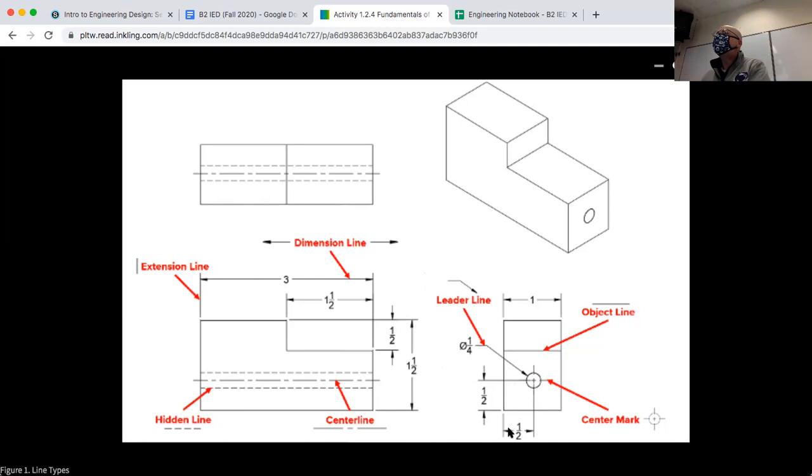Ooh, and look at this. I forgot to tell you that there's actually 2 errors in the example. There's another one I'm not going to show you at this moment, but there's another one that's outside of the view. I never noticed that. But that's an example of sometimes you break the rule when you have to. This dimension you would try not to put on the outside. You want to be on the inside of the views. However, you break the rule sometimes.